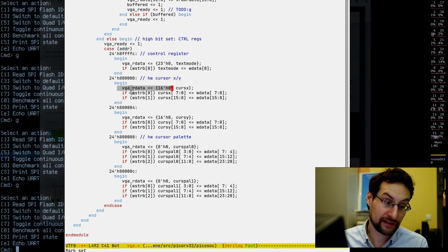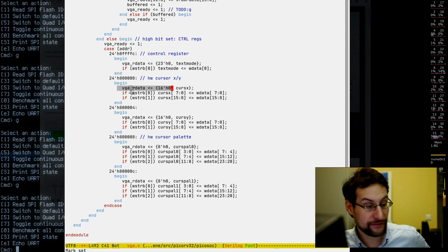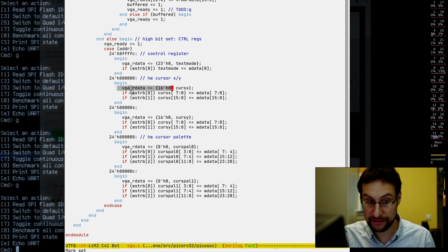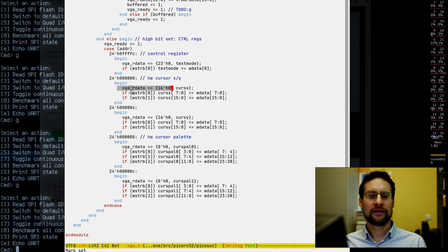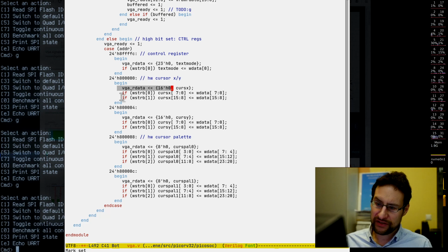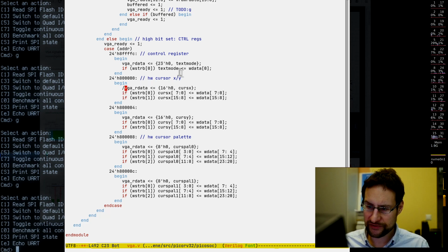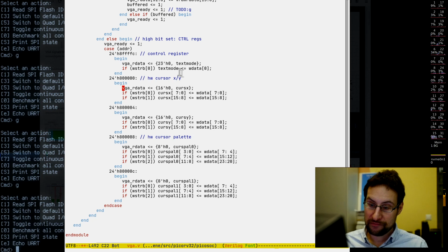Of course, wasting a little bit. Theoretically, we could, if we later for the PS2, by the way, fun fact, I will definitely not do USB, because we definitely have not enough logic elements left after this fancy graphic code. And maybe we even disable, like comment out, this read support, because reading this register of X and Y position is not really necessary. Maybe we just don't implement this, saving us a couple of logic cells for much more important PS2 keyboard and